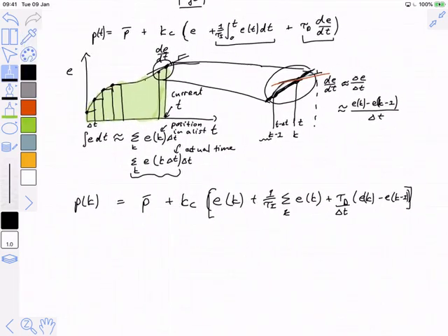And the next step, and so this is problematic in one particular way. We know that there are some problems with saturation of the integral when we implement integral controllers. So this idea of wind-up, where this sum keeps growing even though the controller output has saturated. We have to build into that sum and pull it back again. Also, we have this degree of freedom where we have to choose a bias for the controller.